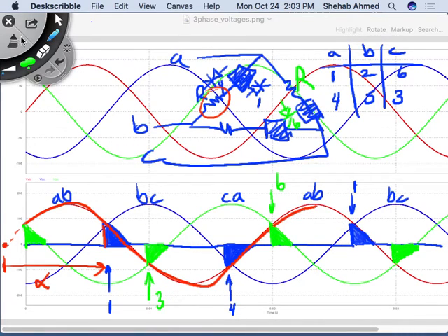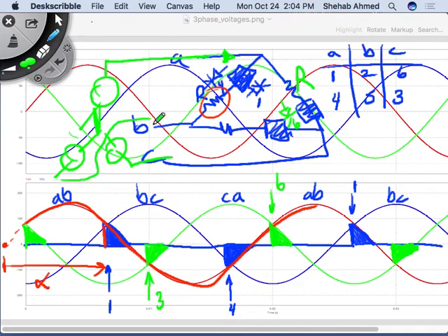How about the current here? Why is this important? Because this is now where my source can be. My three-phase source is here, and typically I'm worried about the current that's being supplied by my utility. This is coming from my utility, my source, and this is my load. Typically my concern is the power factor that the utility is seeing, and the total harmonic distortion that the utility is seeing. Inside your load, you do whatever you want.